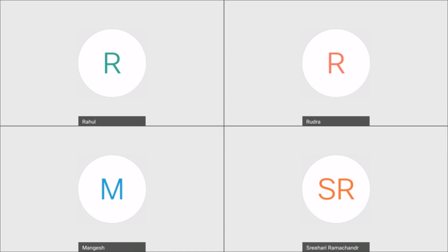But in an asynchronous counter, all the flip flops are basically JK flip flops in toggle mode, or T flip flops. In an asynchronous counter, the output of one flip flop is the clock for the next flip flop. So here we take help of the toggling mode of JK or T flip flop. So let us see.